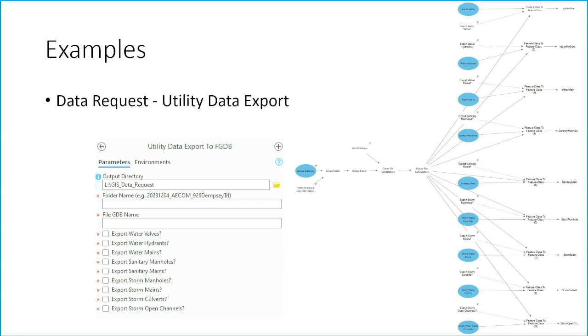So every time I run this, I need to create a new geodatabase before I export the data into that geodatabase. That's the whole idea here: create the folder in which the database is going to go, create the database in which the data is going to go. And then all of these Booleans here are just questions that I created. It's basically a yes, no. And right now, they're all unchecked. It's an empty box, the way that I set these up.